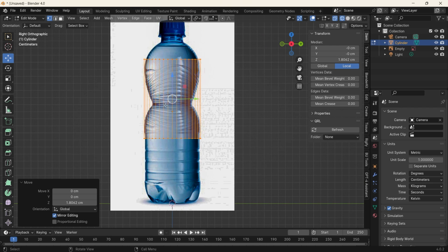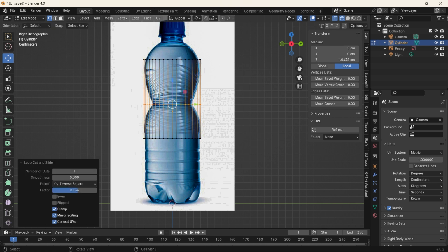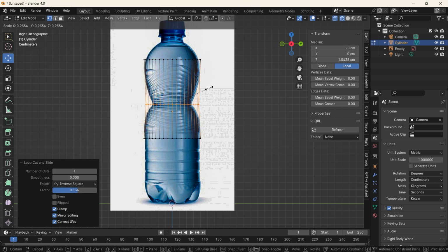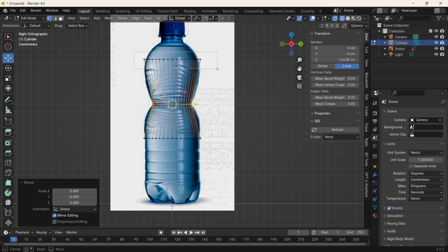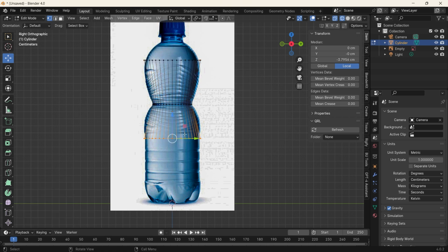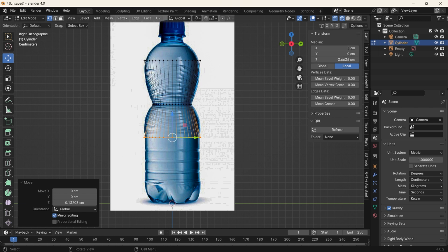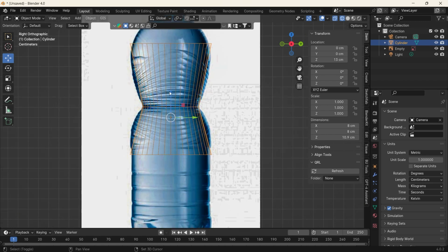Okay, so I'm going to create an edge loop in the middle section over here. So with Control R selected, move it all the way into position. Then I would scale inwards. Okay, so I'll select the top and then move it into place and move this also into place. Do not worry about the outer area not taking shape already. We'll fix that once we're done with the rings.